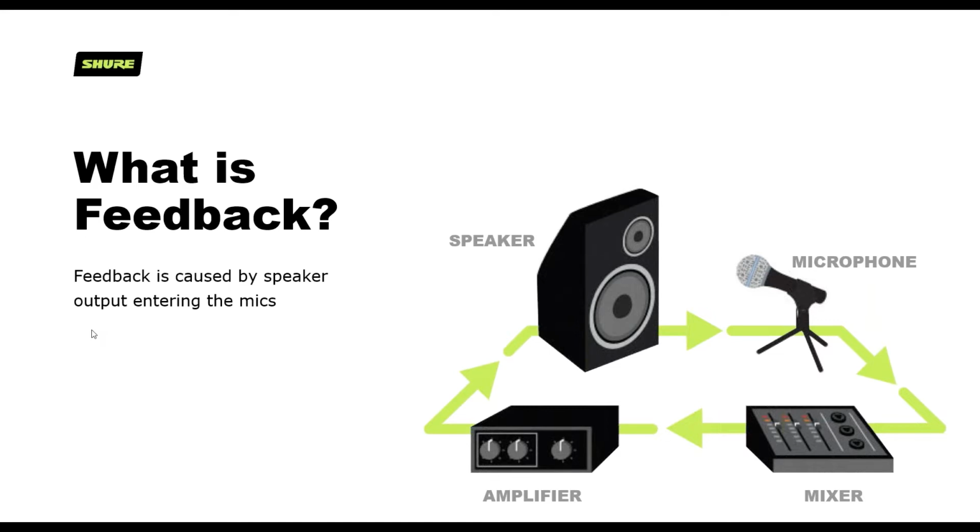First of all, again, what is feedback? Feedback is that squealing or howling sound that you get, depending on what frequency is feeding back, right? It's not buzz, it's not hum, it's not static, it's not any of these other noises. It's that definite squealing or howling sound that is created when you speak or some sound gets picked up by a microphone and it goes through the rest of the sound system and comes back out the loudspeaker at a higher level, and the microphone picks up that same sound again, right? So it's a loop that requires all of these components to be active.